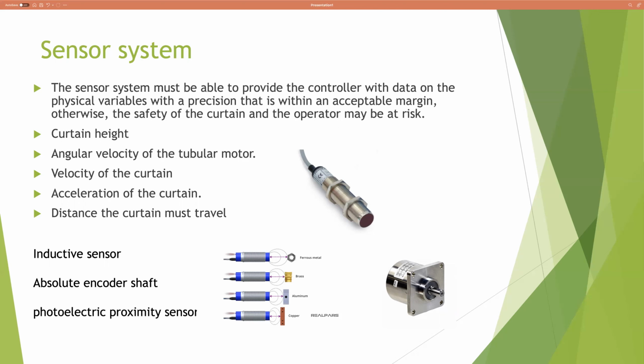We were thinking of using an inductive sensor basically to set limits to protect our machinery, and also for when we enter automatic mode. How we planned on it working, and how I'm pretty sure they all work, is as a true or false, or high or low voltage sensor type, where when they're activated, they send a true signal, and when they're not activated, they send a false signal.